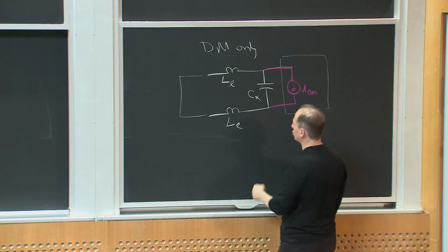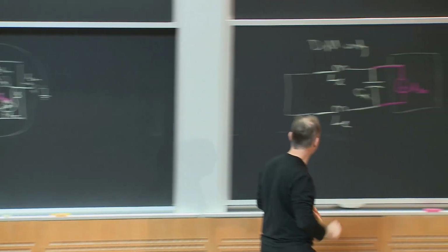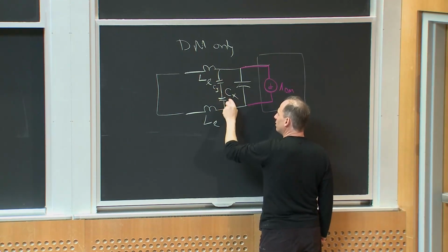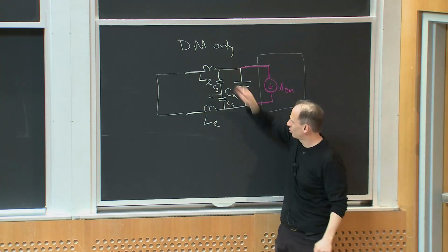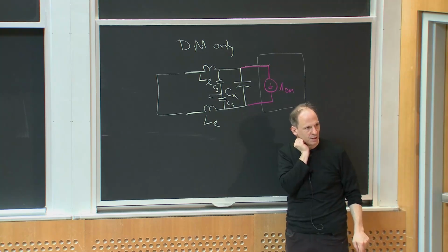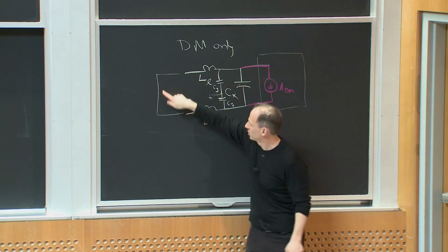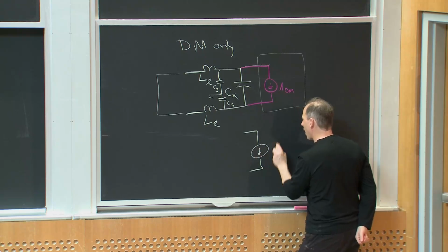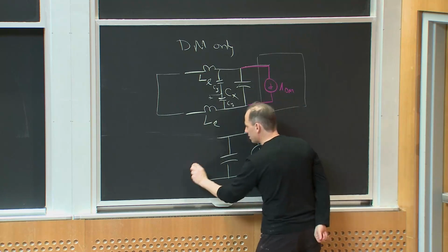I should say we also have the Y capacitors connected to ground. From a differential mode perspective, what that looks like is a Y capacitor here and a Y capacitor here, and the ground is sort of like a virtual open. Nothing's flowing in ground. So these guys just sort of look in series, right? So maybe what I could think of is net controlling the current flow around this loop. What I really have is IDM. I have C sub X plus 1/2 C sub Y.